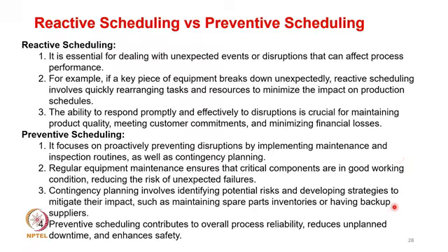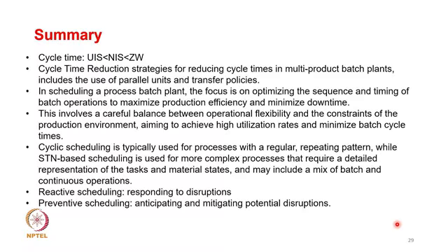Regular maintenance schedules can be integrated, and contingency planning would also help. This is typically done by envisaging what is going to happen, what the potential risks are, and what issues can happen, and integrating them into the schedule to mitigate their impact if such a scenario does occur. Preventive scheduling eventually contributes to reliability and reduces the unplanned downtime, thereby enhancing safety.